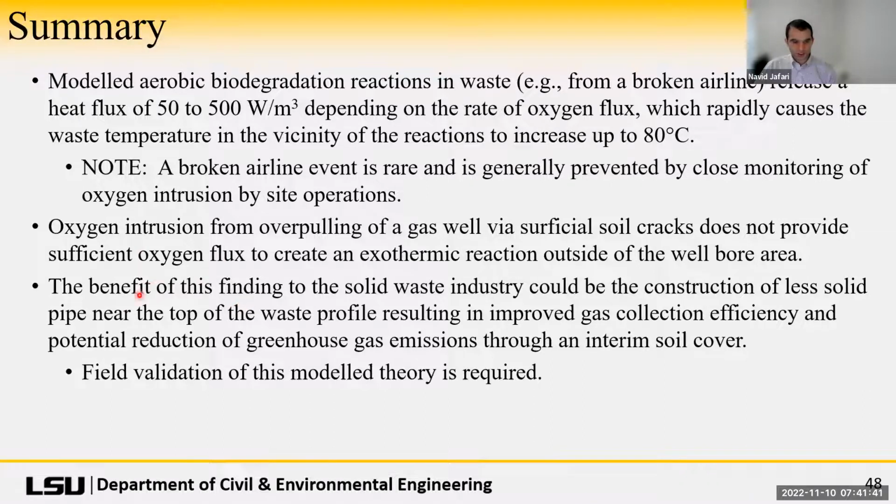But this also shows a benefit. It's not all bad, in a sense. The solid waste industry could produce less solid pipe near the top of the waste profile, resulting in improved gas collection efficiency and reduction of greenhouse gas emissions, meaning that you can probably put that slotted height a little bit closer to the surface, not be too worried about overflowing and air intrusion, and get better, richer gas from that. Of course, in any field, with any modeling, you need field validation.